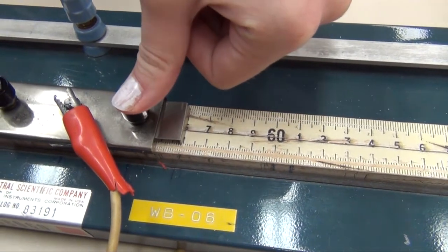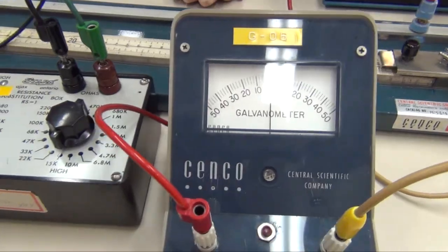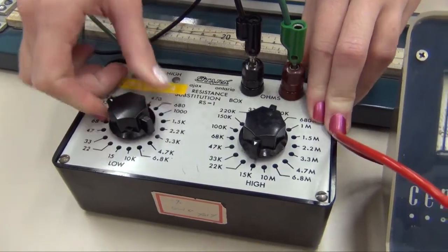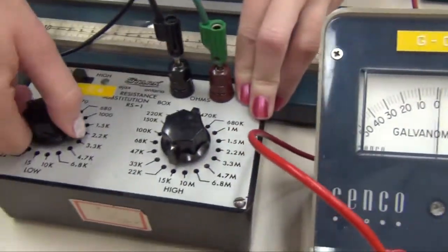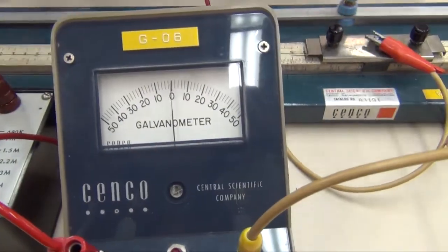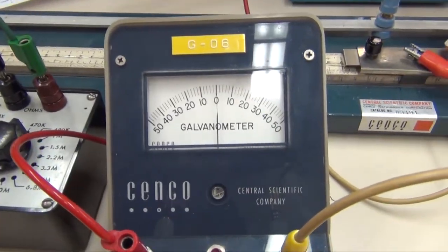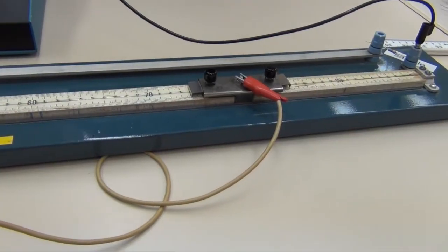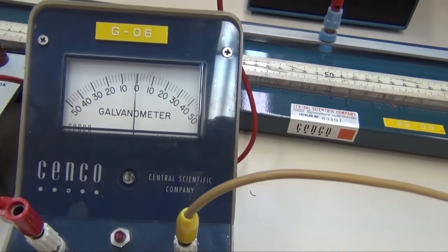Depressing the contact key at the center of the meter stick completes the circuit and causes the galvanometer to deflect one way or the other depending on which is larger, your sample or your reference resistance. First, set the resistance box as close as possible to the sample by changing the resistance until the direction of the galvanometer deflection changes. Next, slide the contact key along the wire, depressing it at various points until there's 0